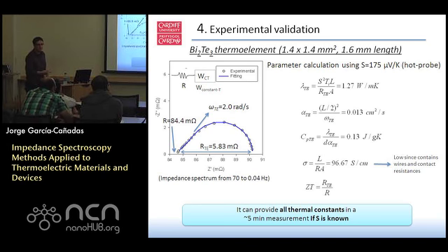You can't do 4-wire measurement? Yes, you can. The experimental setup becomes a bit more complex because you need to spot weld wires or attach 2 more probes. But in principle, the way to extract directly the electrical conductivity of your material is using a 4 probe.